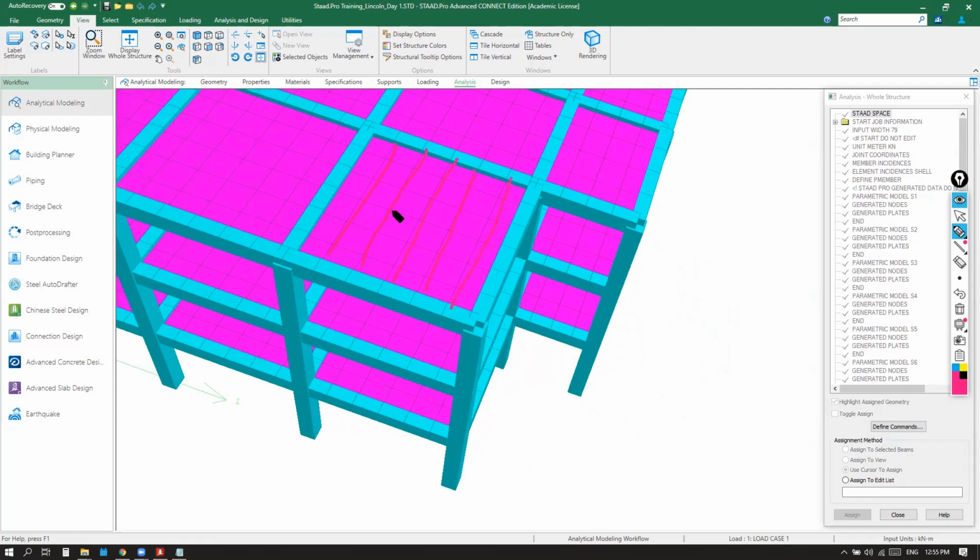So for designing the slab in the finite element analysis, we need to have the meshes, not only for a slab, but also, as you can see, for the beams, I have some sections, because these meshes actually divide the beams as well. See here, it is continuous.